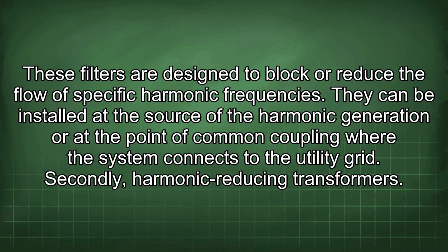These filters are designed to block or reduce the flow of specific harmonic frequencies. They can be installed at the source of the harmonic generation or at the point of common coupling where the system connects to the utility grid.